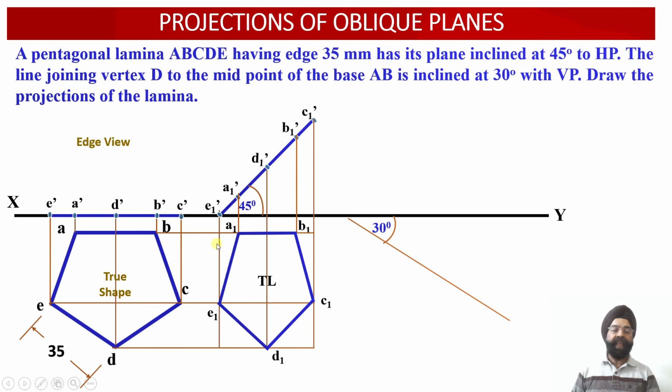So we know that this is the rectangular projection, and we also know that at the midpoint, if we draw a parallel line, this edge will be obtained, and at a distance of this much from the point D, if we draw this vertical line, all these points we can obtain over here. Let us draw this rectangular box which is going to inscribe this pentagonal top view projection in such a way that this midpoint line, which corresponds to the true length of D1 with the midpoint of the edge AB. So this is this particular edge which is a true length.